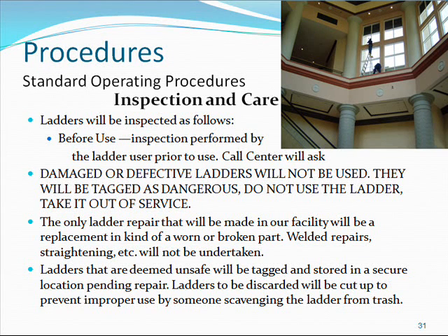The only ladder repair that will be made in our facility will be a replacement in kind of worn or broken parts. Welded repairs, straightening, etc. will not be undertaken. Ladders that are deemed unsafe will be tagged and stored in a secure location pending repair. Ladders to be discarded will be cut up to prevent improper use by someone scavenging the ladder from the trash.